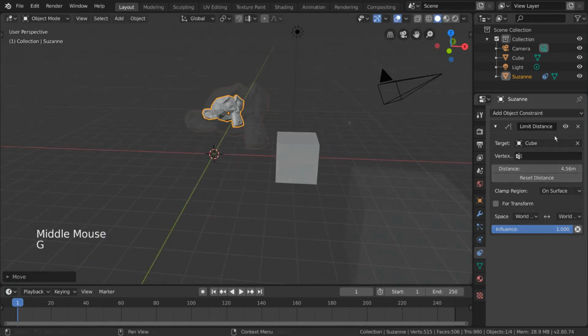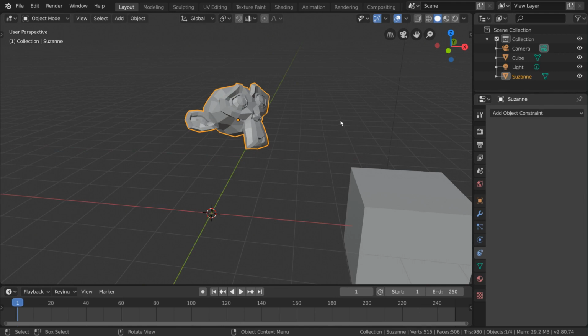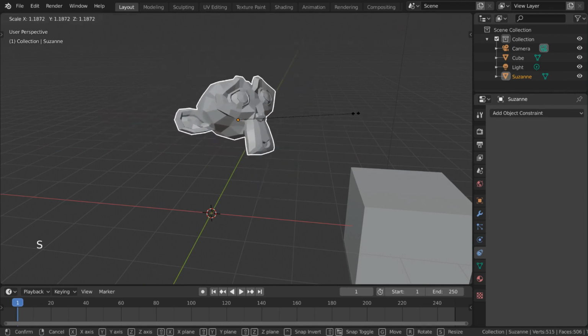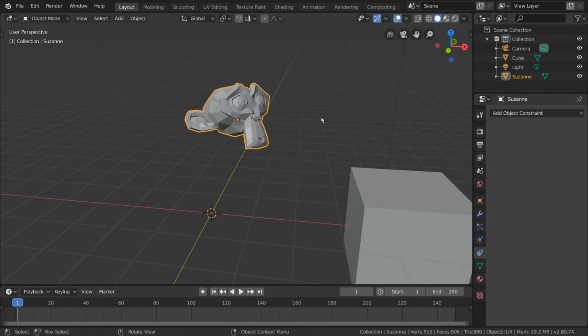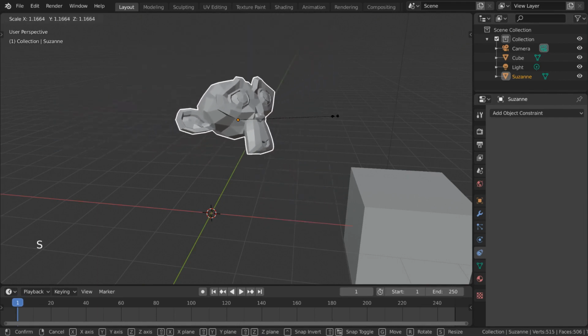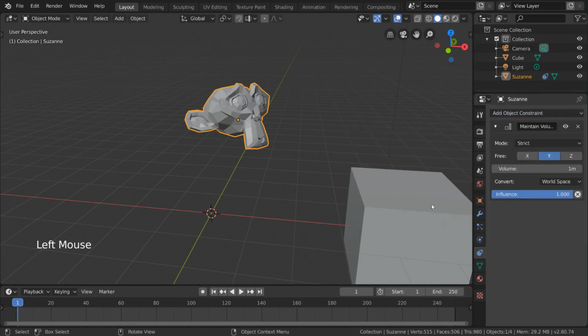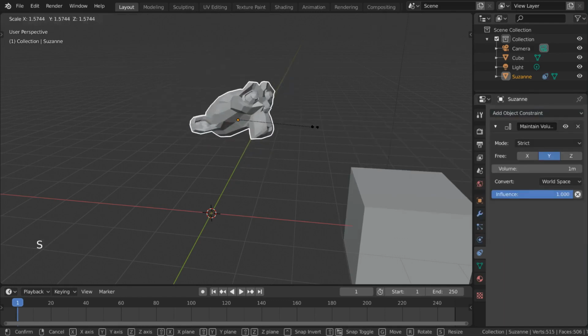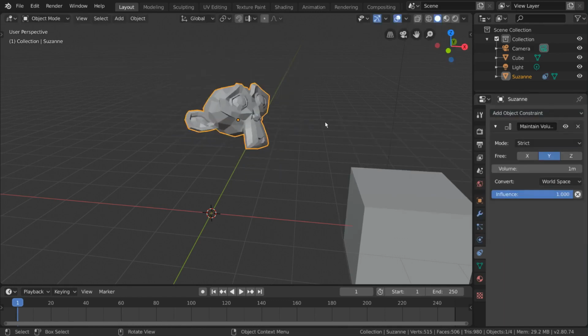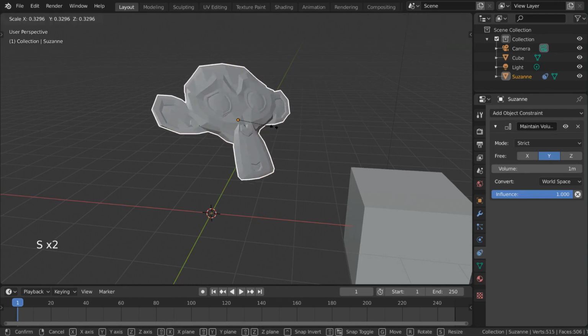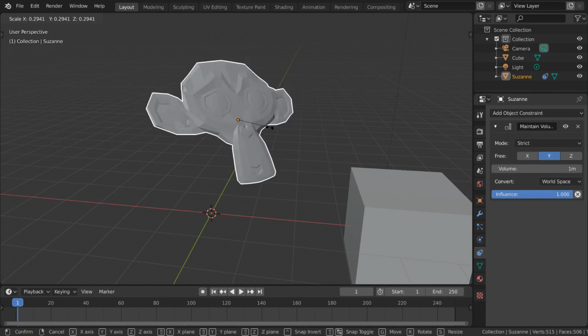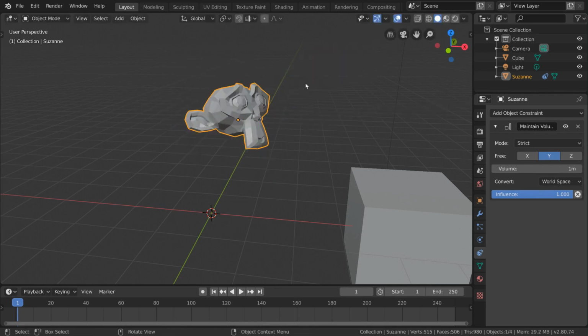The maintain volume constraint prevents objects from freely changing their scale. Typically, when scaling an object, the volume of your object gets increased for free. However, with maintain volume, it restricts you from gaining free volume, forcing your object to bend and contract while scaling, just like a real volume would if forced to change size. However, the volume input value is a world value. Therefore, you'll need to know the neutral volume of your mesh.